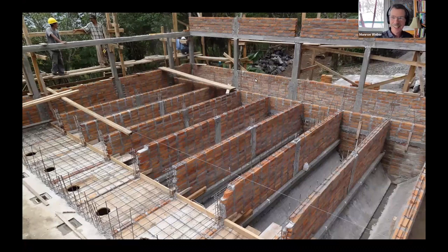Oh, and you notice brick walls in here, no overlap between bricks. Brick walls out here look conventional. The bricks are like this. Do you see that difference? Walls that have to hold back water, the bricks are on top of each other so they can run rebar in them. Walls that are just building walls have bricks overlapping and they're not reinforced. See, if I hadn't pointed that out, you might not have even noticed that those bricks were different, right?